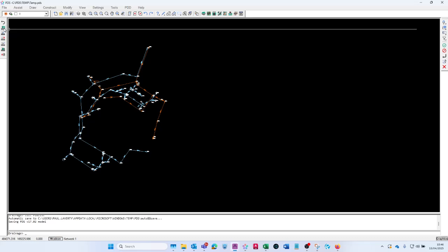Now if you've been working with the road or the ground modeling, by now you would have the proposed ground model, the DGM, loaded into your drawing to get your spot levels and such like that. However, you need to do an extra step with the drainage, because you have to assign the ground models for the drainage to generate these profiles so it knows where to get the surface levels. If you do not, I'll show you what happens.